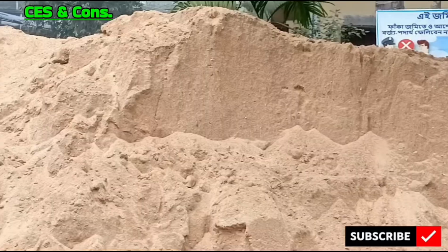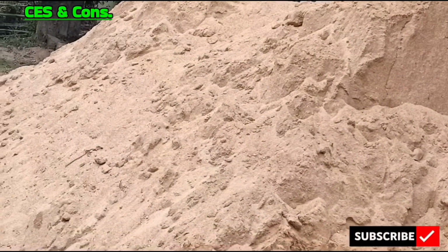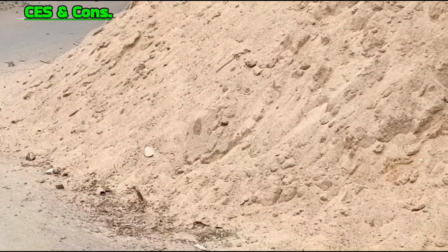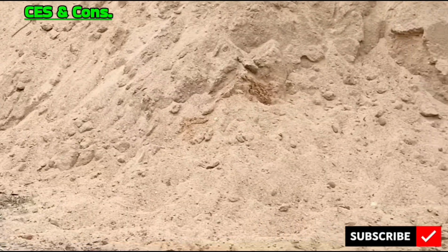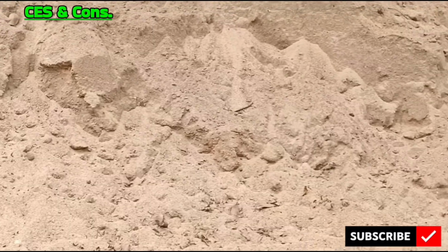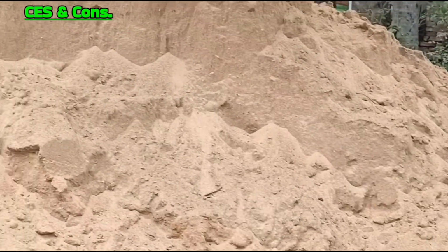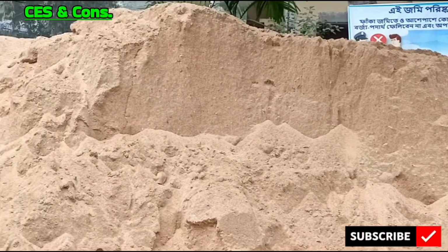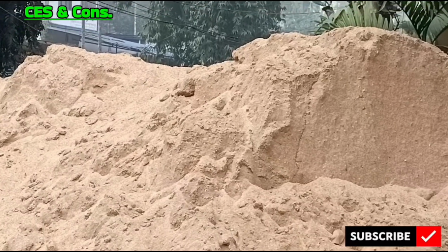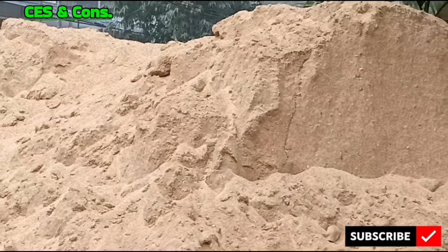The sand should be clean, free from silt, clay and organic impurities. Silt content should be less than or equal to 3% by weight when tested as per IS 2386 Part 1. It should not contain any harmful impurities like alkali, salt, which might cause corrosion. Fine aggregate should have a fineness modulus of 2.6 to 3.2 for most concrete works. Sand exhibits bulking when moist. This must be considered during proportioning.